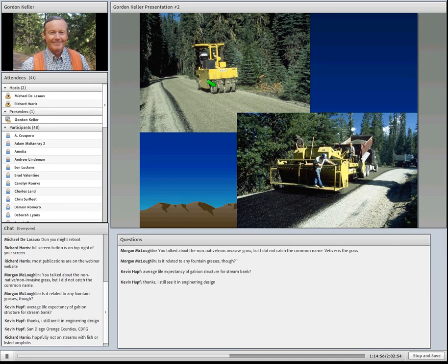And this can last, if it's well built and not abused, from 7 to 10 years. Most of what look like paved roads in North or South Africa, Australia, New Zealand, most of their roads are actually chip sealed roads. They're not actually hot mix asphalt roads. But they also have a lot of good quality control because they do it a great deal. And our problem is often quality control because we don't do it enough.